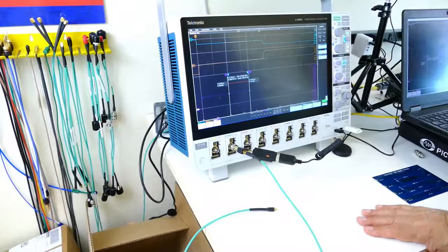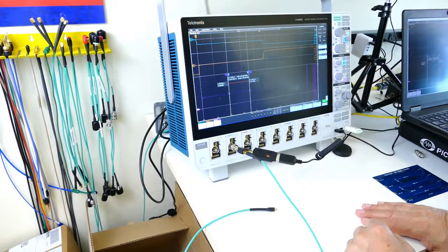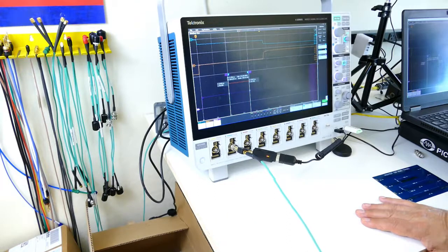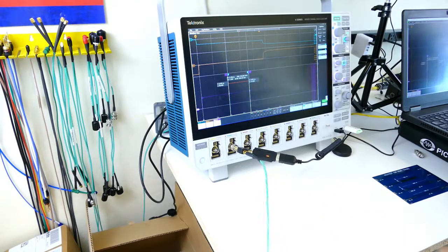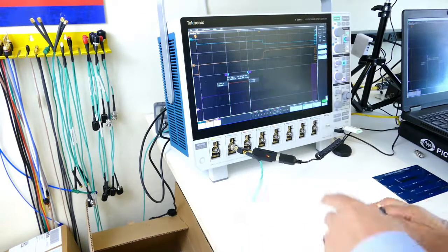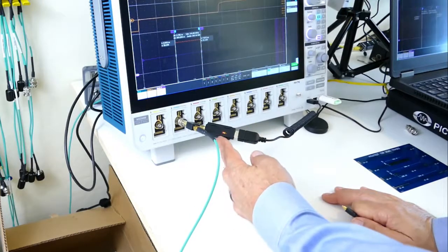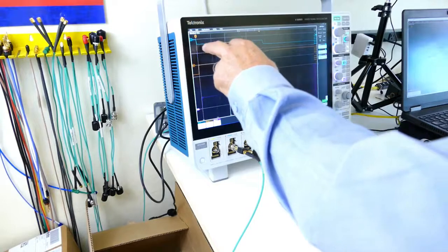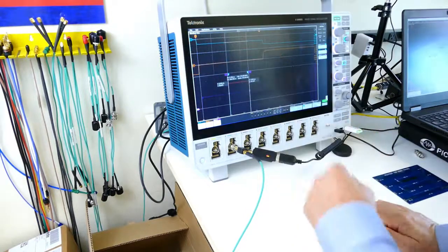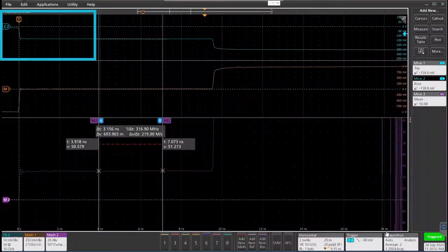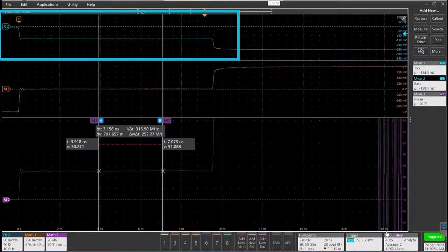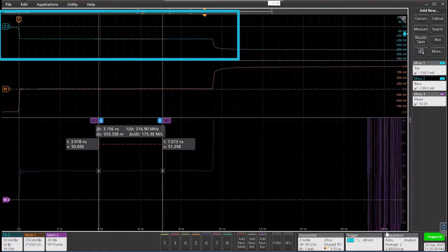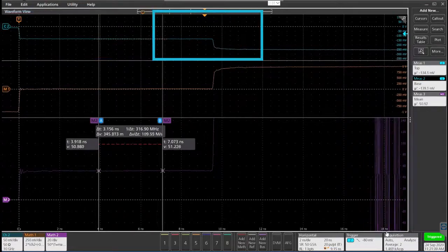The other thing that we use this TDR for is to check the cables and our printed circuit board traces, including the printed circuit board coupons. So I'm using the same generator, 32 picosecond edge, so 10 gigahertz bandwidth. And the top trace here, we're looking at the voltage generated by the signal. And here's the zero level, here's the plateau, and that plateau is generated by the cable. So that's actually the measurement of the cable. And then this is the end of the cable here.